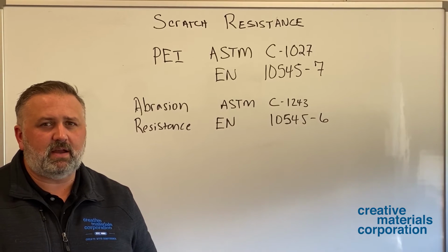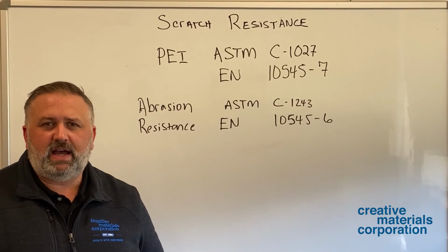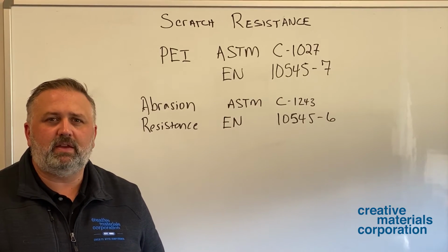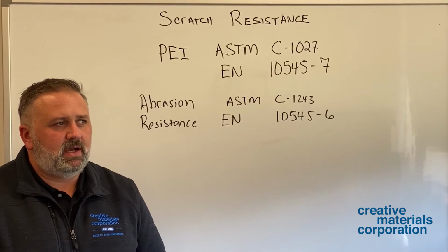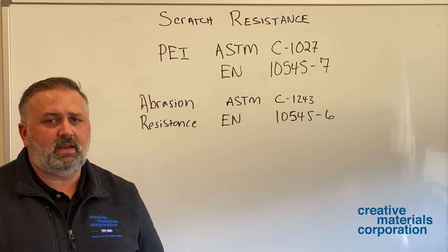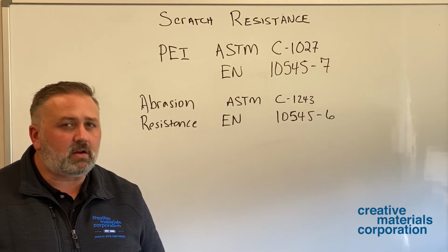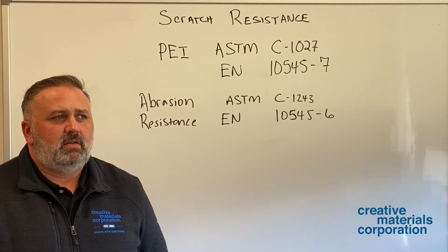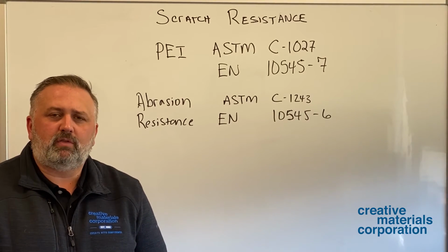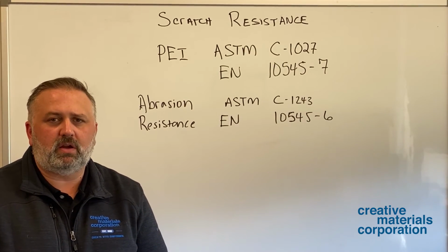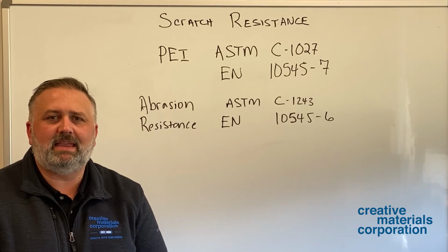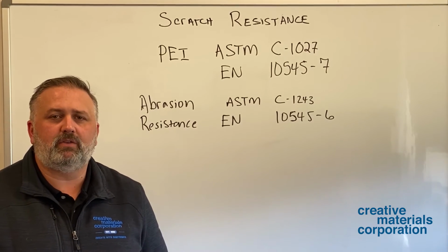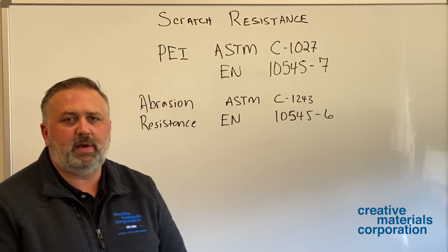Most of the glazes that are out there now are 4s and 5s and suitable for heavy duty commercial projects. There are some that are in the 3s that you have to be careful with, generally darker colors in the range. But what we're looking for there is when the tiles are walked on over time, how resistant is that glaze to wearing off over patterns. Obviously the higher the result, the better.